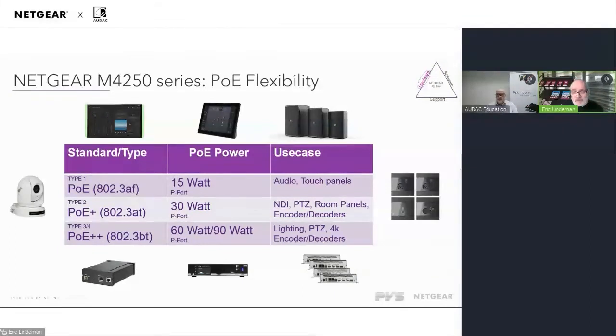The loss will be 5%, but the switch also compensates the loss by knowing the cable length and powering up the wattage a little bit with a correction. So as long as you keep to the cable length, 100 meters is the max for workable power at the end. Okay, great. Thanks.